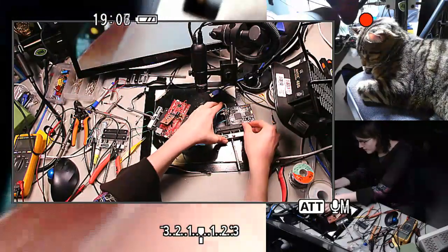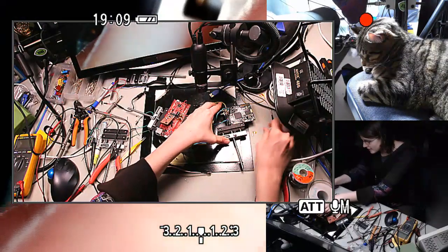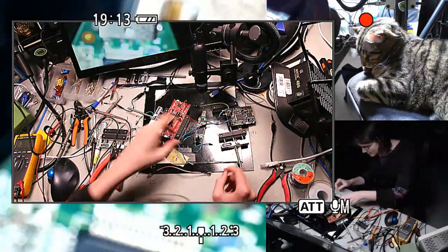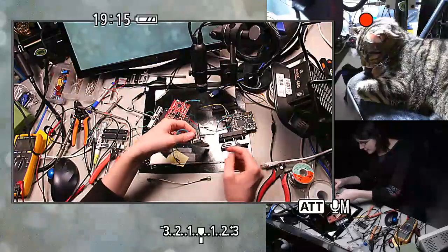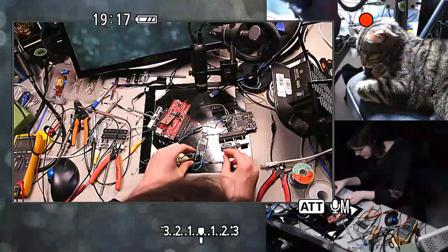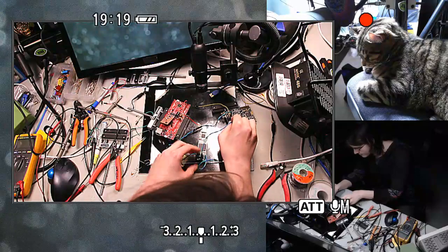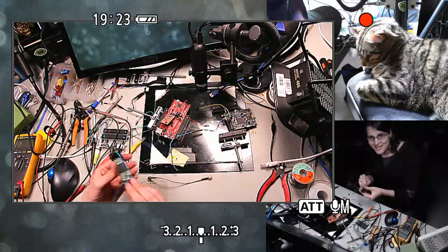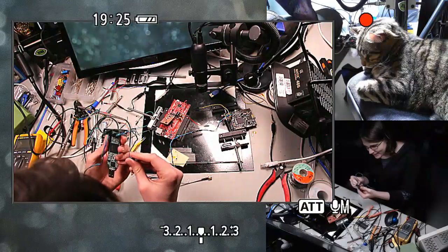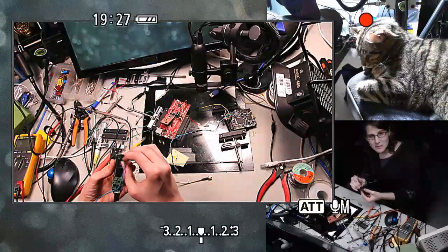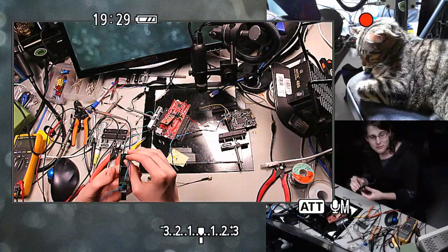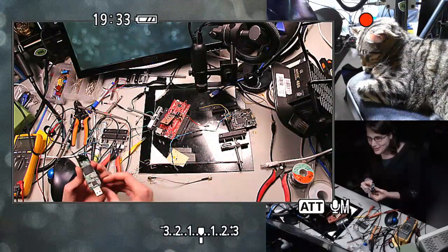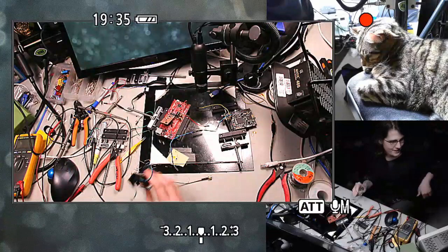And so it wouldn't really surprise me if the PHY on that chip was not especially great as far as its analog design. It's also really power hungry for a 10BASE-T chip. I seem to remember it wants to draw a couple hundred milliamps even when it's not doing much, and so it gets pretty warm, and yeah, it's not so great.